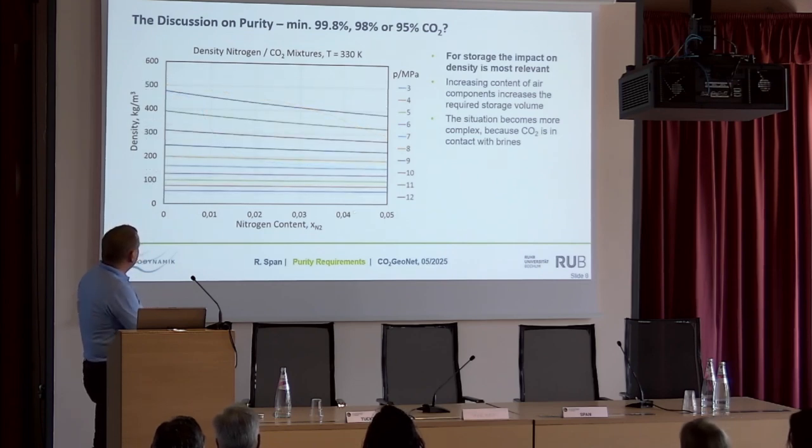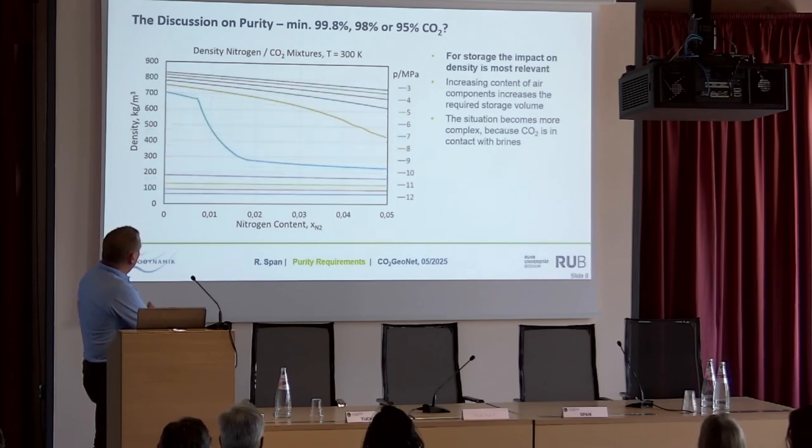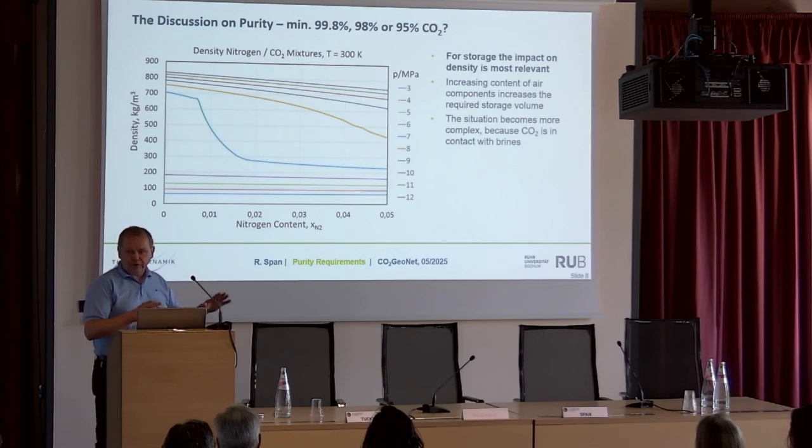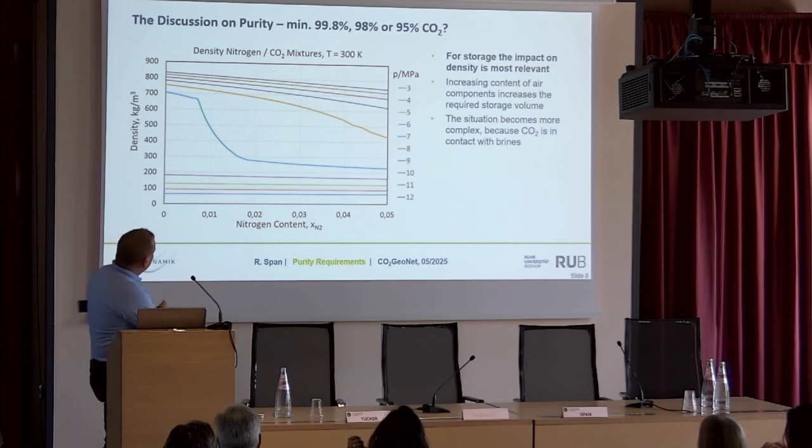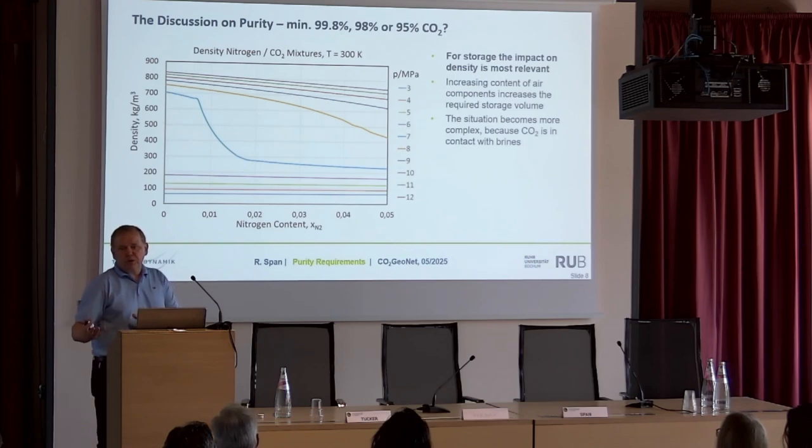density plotted over nitrogen content. Sorry, one too far. And what you see is that with increasing nitrogen content, the density decreases. Of course, there's an additional effect because now you also store nitrogen, but the density of the mixture decreases with increasing nitrogen. At high pressure, this effect is not very pronounced, but there is a pressure range where this effect is very strong, and that's because a nitrogen-rich gas phase is built.